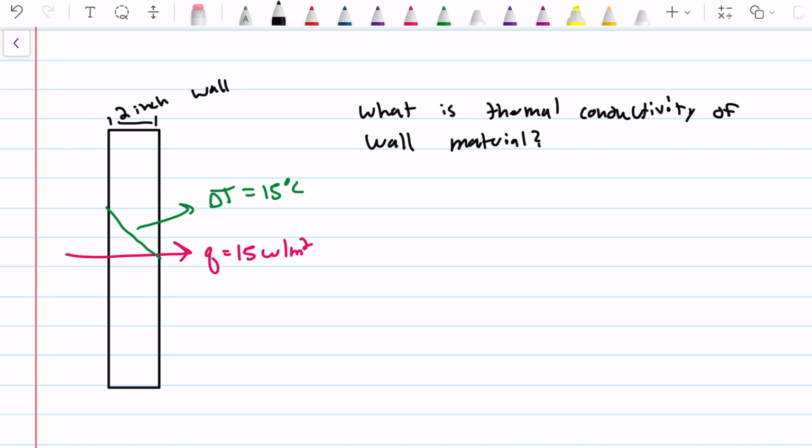And Fourier's law is an empirically derived thing, and it says that the heat flux is proportional to a drop in temperature, and we can equate these two by having this constant that we call K. Well, actually, hold on. This is not dT. I was a little bit wrong here. This would be dT/dx. So let's call this delta T over delta L in our case.